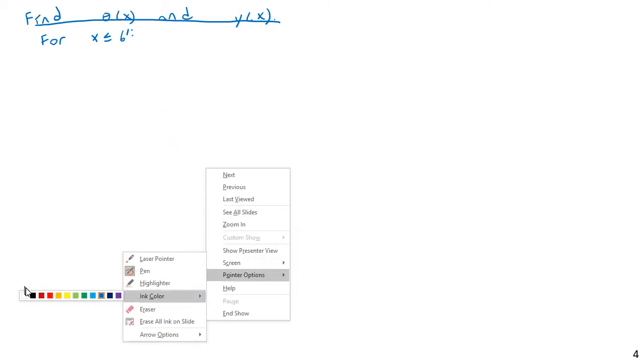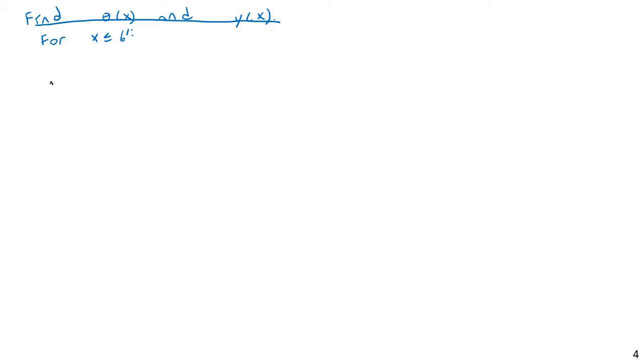So we have the formula that we developed previously, that theta as a function of x is equal to the integral of moment divided by EI. Or I could say that theta 1 as a function of x is equal to the integral of M of x over EI dx, which will be equal to 1 over EI, and we're just going to do this integral in terms of EI.